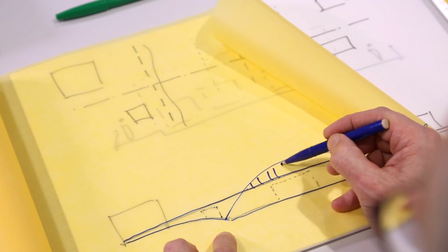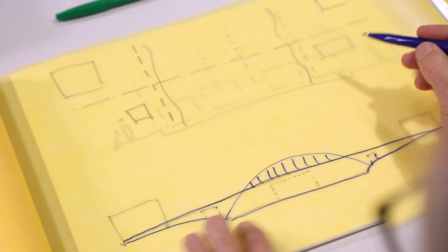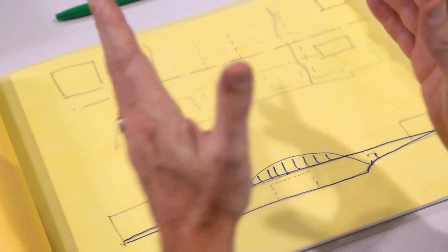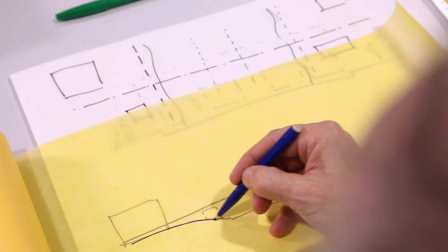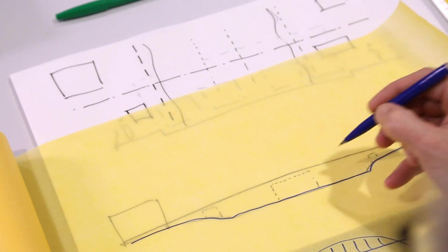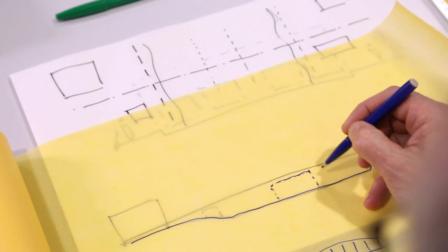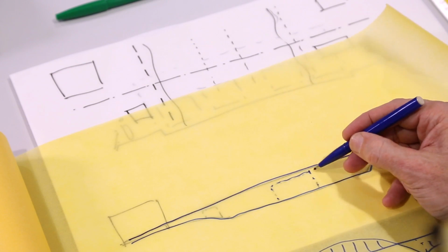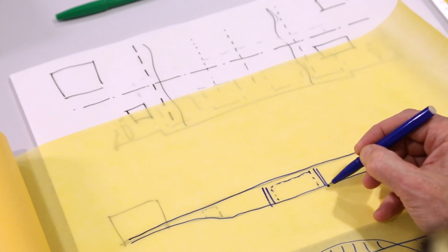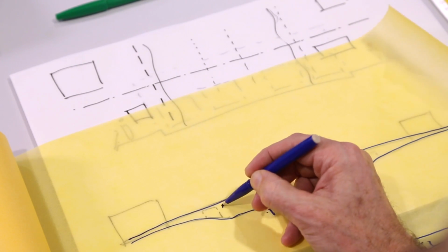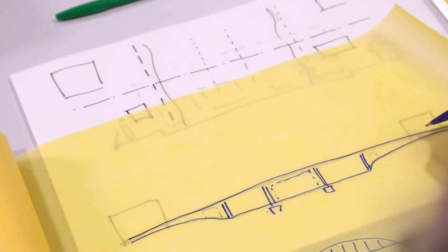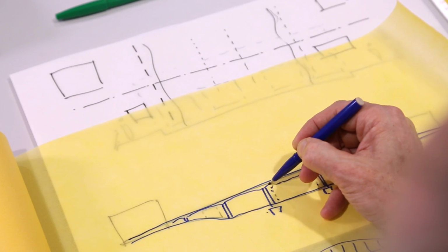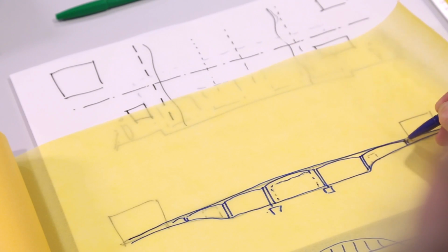But we've then got to support the bridge deck with some hangers, and the deck can be quite thin because we can support it at close centres. But another option, of course, might be to say, okay, well, actually what we're going to do is just do the minimum span that we can get away with. There's that line again. Now we can support it here and here, assuming we can build foundations in the water. And maybe we put another support at the edge of the river, and maybe we've got another one back here somewhere. And all of a sudden, we've got what looks like a fairly conventional continuous bridge.